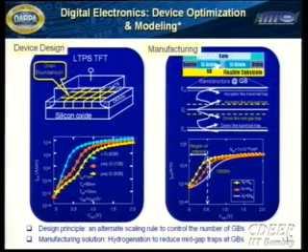These are some of the other ones showing more details of this manufacturing process. But the more important thing to note is that you can have different kinds of variation; absolutely, you don't have repeatability, so we'll have to talk about it. The modeling technique that we used is basically having these different grain boundaries. I'm showing the channel region, which was divided into several areas where we could decide to put a grain boundary or not. This work appeared in the Transactions on Electron Devices, published I think last year or the year before, again using the design principle that I just talked about.